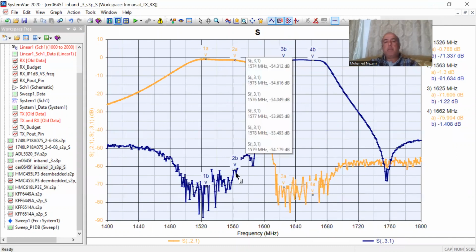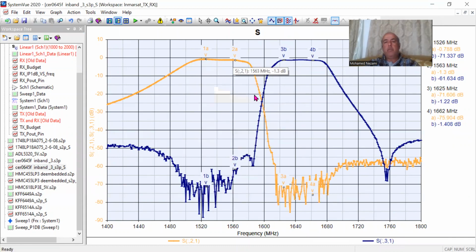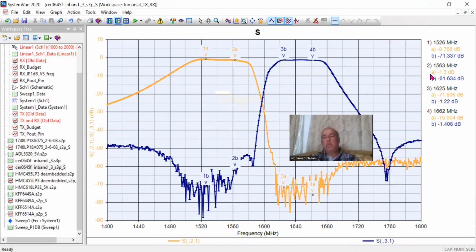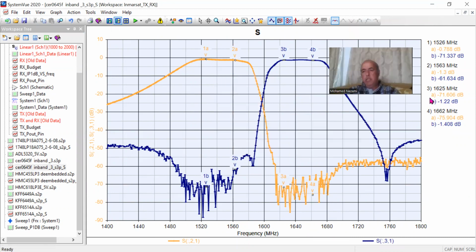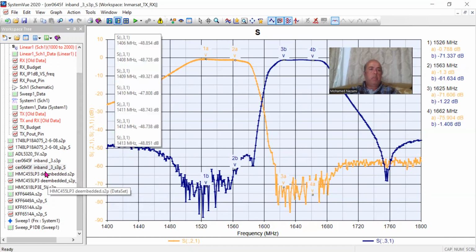So this is the diplexer, with both the receive band and the transmit band. And you can see the loss, this one is really optimized for the receive path. So we start at 7/10 of a dB, 8/10 of a dB, to 1 and a little bit dBs of insertion loss, while the transmit side has about 1.2, 1.4 dB, okay?